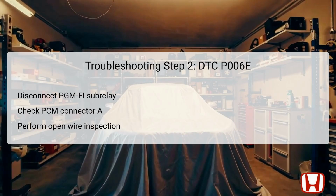In this second step, the PGM-FI subrelay is disconnected, which is essential for isolating the circuit issue. With the subrelay detached, inspect the PCM connector A, specifically the female terminals of the 50P connector. A thorough visual examination is recommended to identify any possible damage or oxidation, which may affect the connection quality.